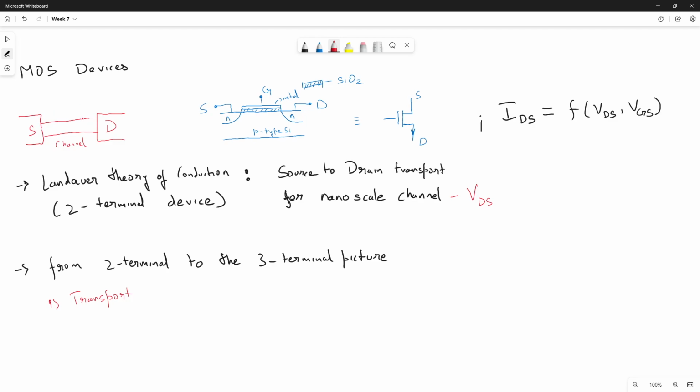If there is a potential drop of V, essentially what happens is, on an average, and this is not exactly what is happening, but on an average, there is a potential drop of V by 2 jumping from the source to the channel, and there is a further drop, energy loss, when we move from the channel to the drain. So all the resistance effects that we are calculating essentially come from the channel, source drain interface.